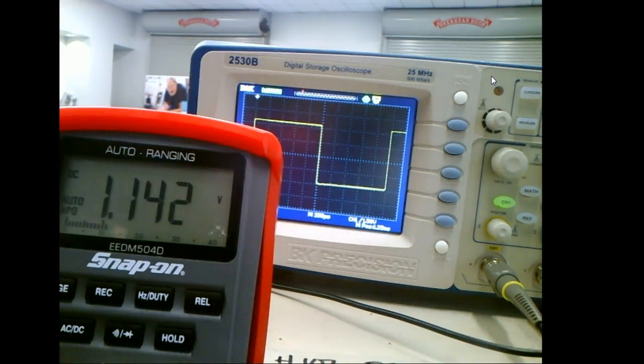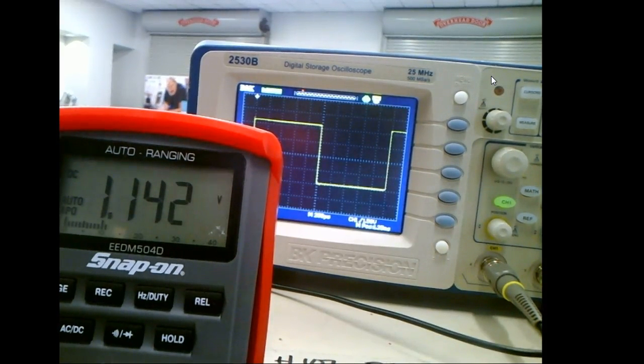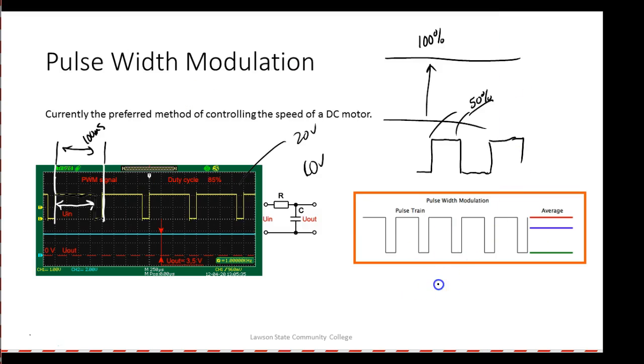But what happens to any motor you load down? It's going to slow down. So we would use an encoder or something to bring back the speed and put a closed loop in there, and then we set in a set point. The way a closed loop system works is we come in and put a set point. This is what we want, right? You understand? And then we bring back a what?